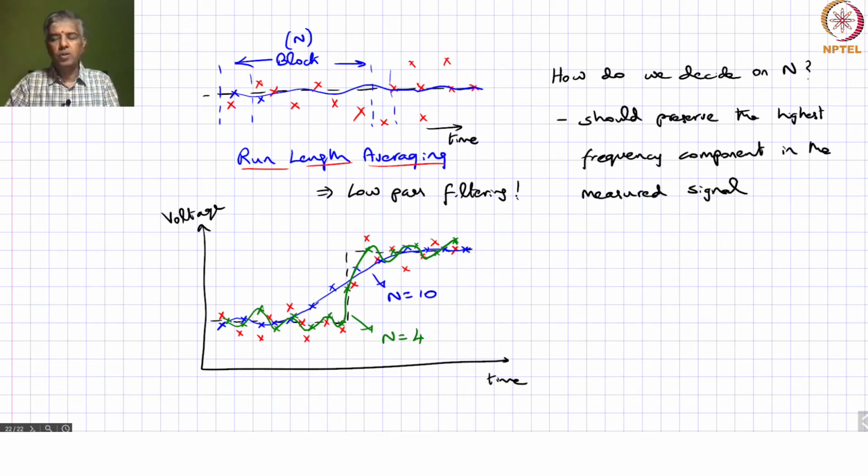If you want to extend the cutoff frequency of your low pass filter so that you can bring in some of the high frequency components, you also start bringing in noise, and because of that the improvement in the signal to noise ratio may not be as high. So that's something you have to be very conscious about.